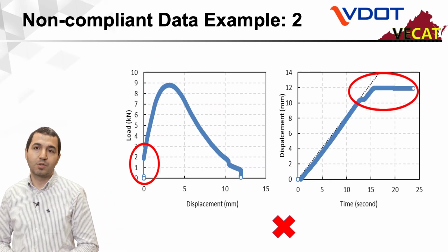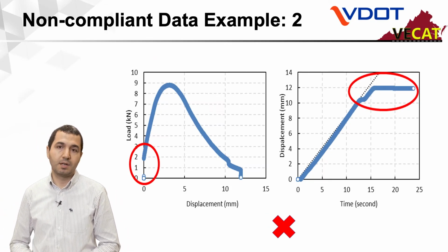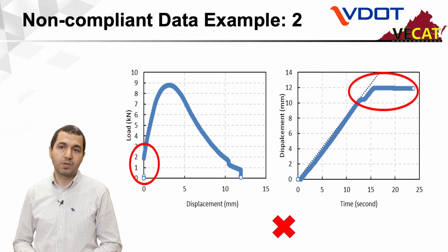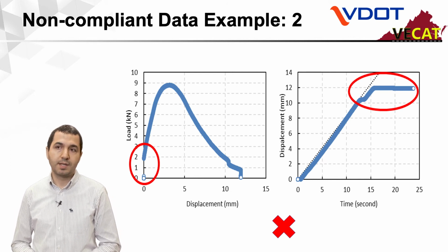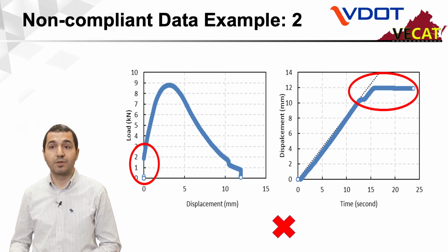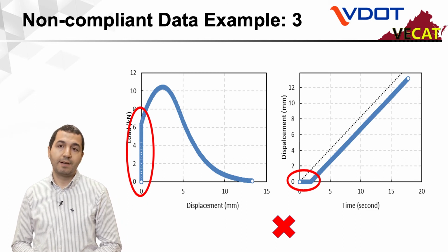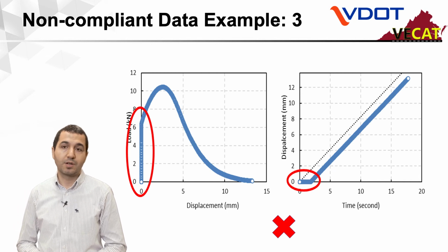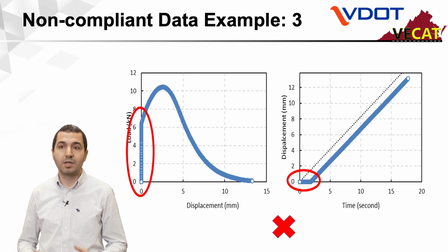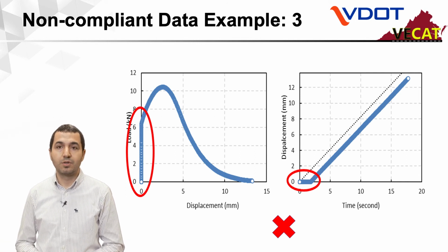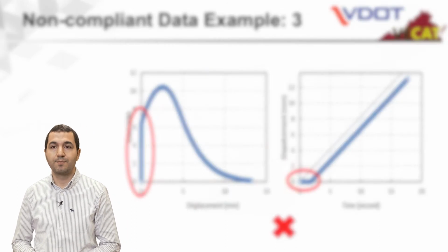And in here, some sort of glitch happened at the beginning of the test that it didn't record the displacement. And then also towards the end tail here, we see that probably the LVDT range is exceeded, therefore making this bad data, so the test has to be repeated for this case too. Another example here, load is recording but not the displacement. Perhaps there is a synchronization issue with this, so machines have to be calibrated on a regular basis to prevent such errors with the test.